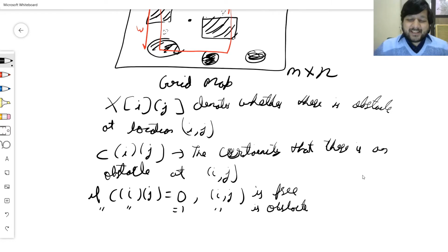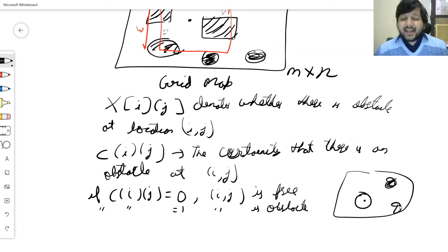The proximity sensor is something like a laser at the center of the robot, and it sends a laser beam, it strikes an obstacle and gets back. So it reports that this definitely is an obstacle and all these areas are free, and similarly the beam goes all around. It can also have a stereo camera. The stereo camera looks at this thing, it says it's an obstacle, and because it's stereo, it also gets the depth at every point.